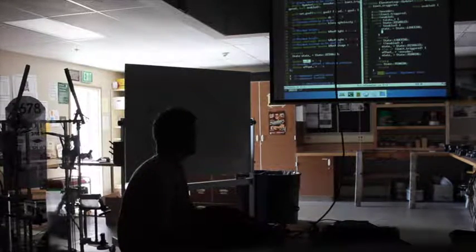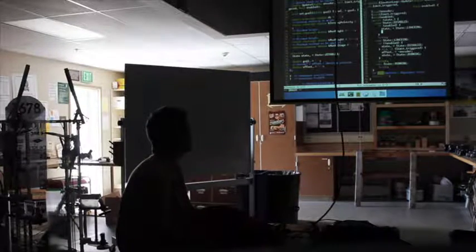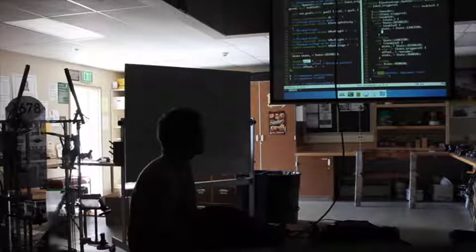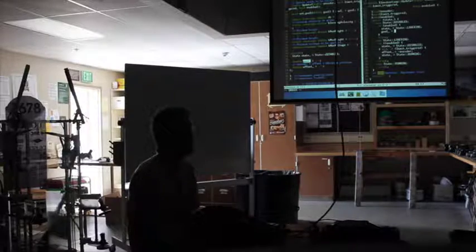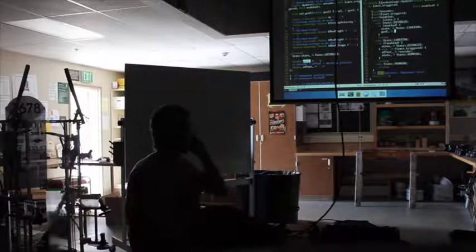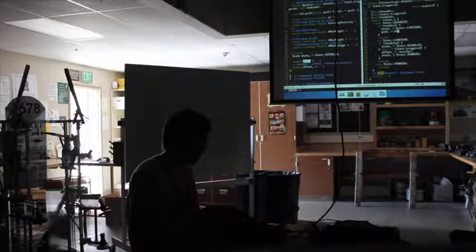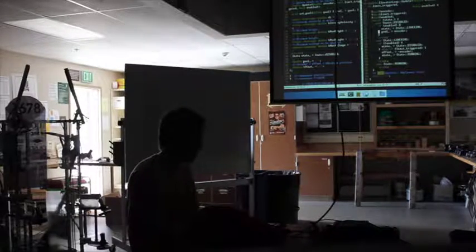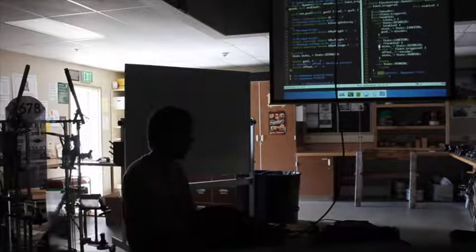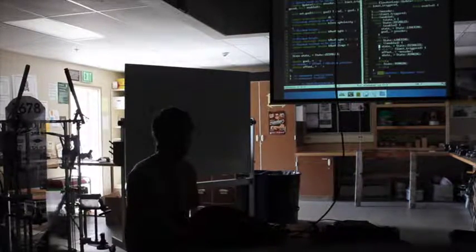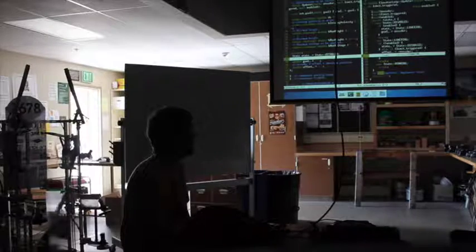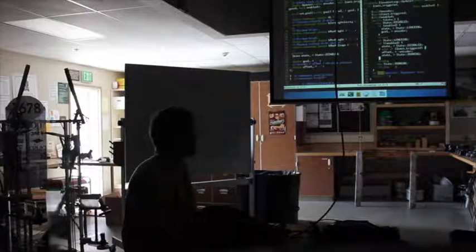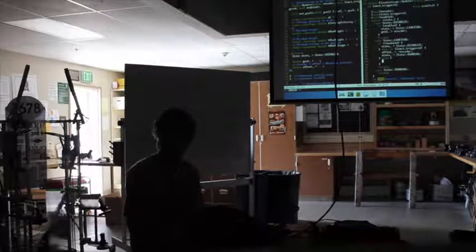So what we want to do is figure out how to generate a goal to do this. Conveniently, we have a goal. Actually, we'll start with this, and then there may be some more complications. So we want to tell it to start where we currently are. How do we do that? That's your encoder. Okay, good. And then if we're lowering, if we're disabled, we go back. We don't really need to update our goal. If the limit's triggered, then we're zeroed, so we don't really need to update our goal. We'll let the next case handle it. Otherwise, we want to move down slowly. How do we do that?